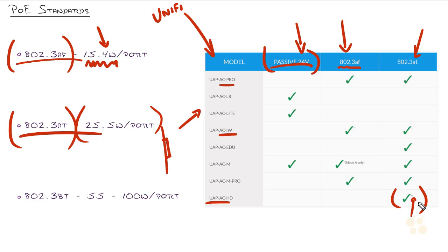I don't know exactly what that means, but what I will say is a lot of devices that support 802.3at will support a lower wattage, but it will disable some of the higher capacity features. For example, you might have a video surveillance camera that works just fine with 802.3af, but maybe the motor that allows you to rotate the video camera around will not function.